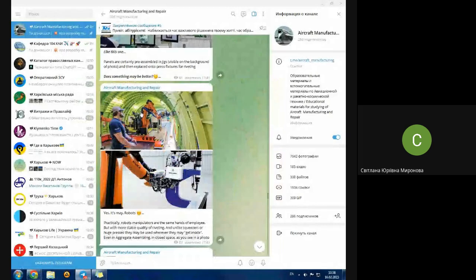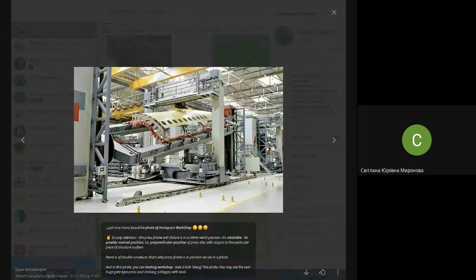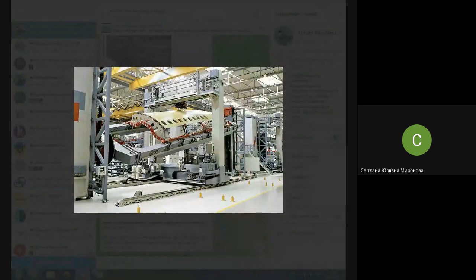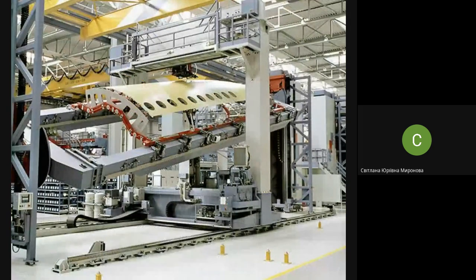But if we break down the structure into pieces like assembly units, panels, sections, we may do the work in parallel. On one hand, it reduces the time of assembling altogether. Labor input may be the same, but the time of assembling is less because we're working in parallel. And on the other hand, in this case, we create pieces with open access for joining places.